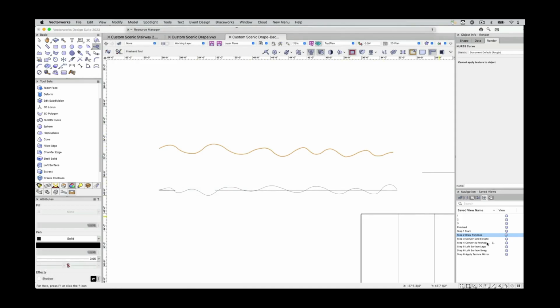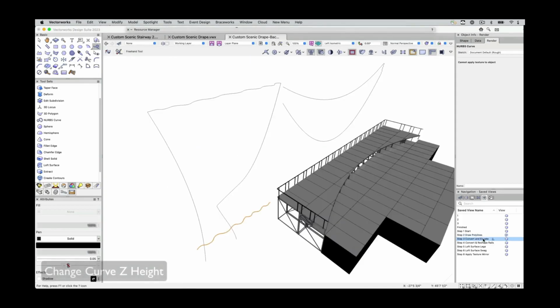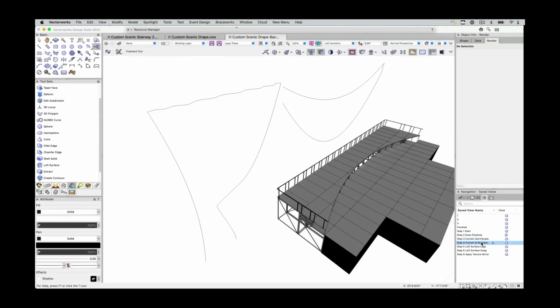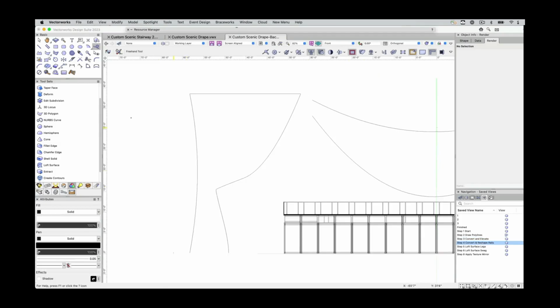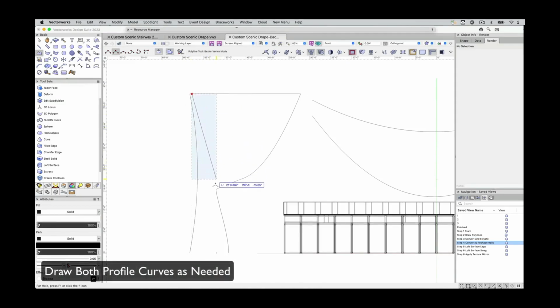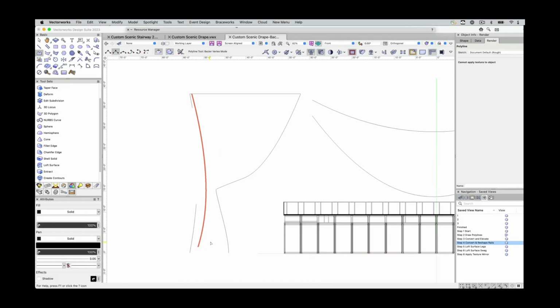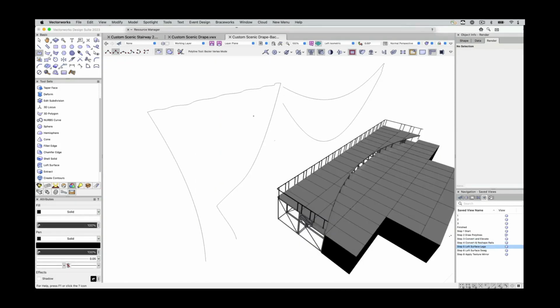So when we have this line, and then from the front, we're going to make the rails. Look at it from the front, and we'll just use the polyline tool once again. And we created those curves. I'll delete that one. We already have one. And then we did the inside one in the same method.